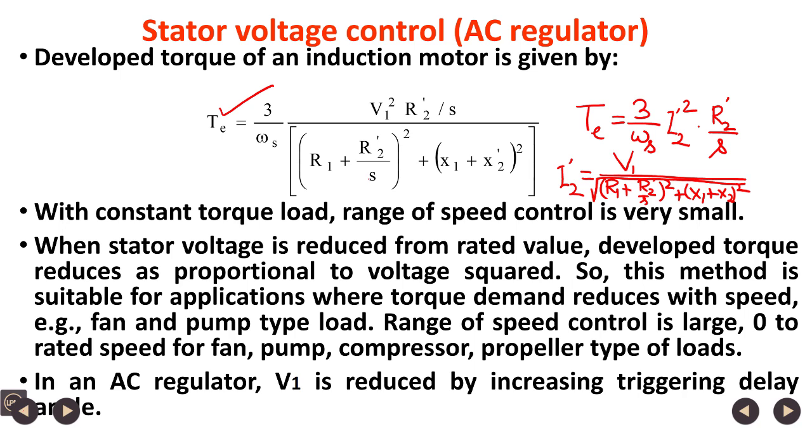When V_1 is controlled, at steady state the electromagnetic torque T_e equals load torque plus viscous friction torque, since inertia torque at steady state is 0. The electromagnetic torque is balanced by the load torque, so when the voltage is varied with the torque fixed, the slip changes with voltage and the torque balance is obtained. So motor speed changes with voltage. This is the principle of speed control.